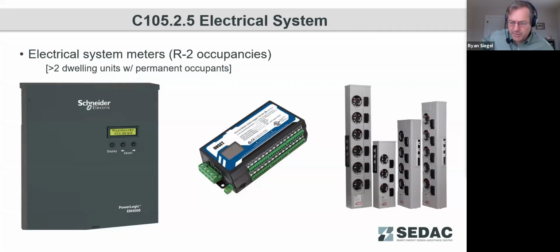So if all of a sudden they see a particular dwelling unit with, this may be for areas that have heat pumps with electric resistance backups, it may be such that a unit malfunctions, and all of a sudden you see a real big spike in electric consumption of a particular dwelling unit. And so the building engineer may know to go investigate what is causing that dramatic jump in use.